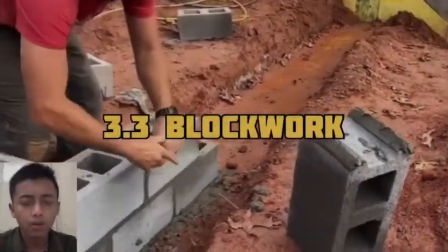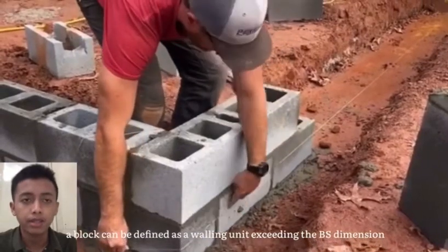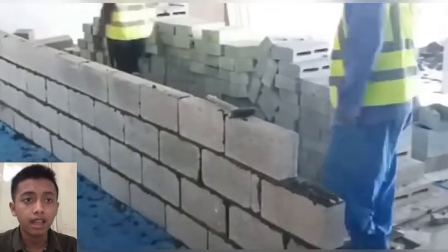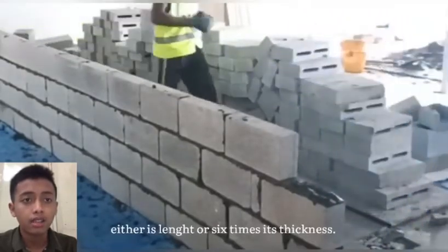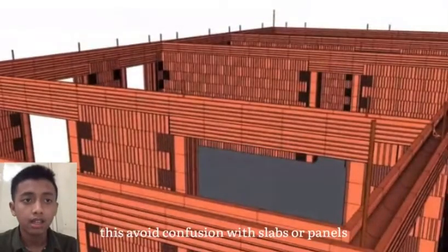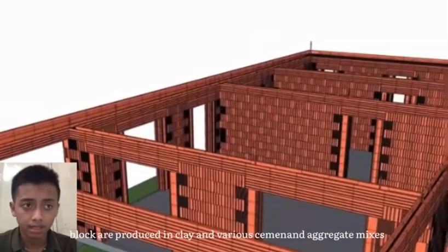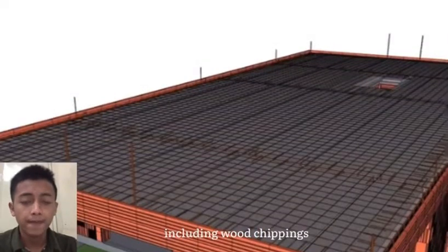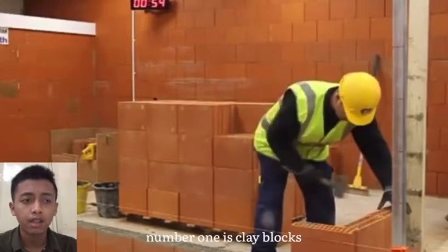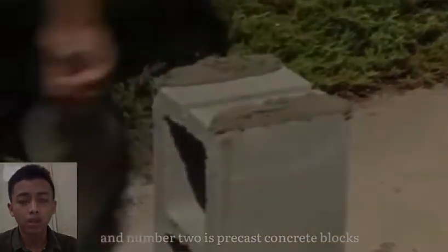3.2 Blockwork. A block can be defined as a walling unit exceeding the BS dimensions specified for bricks, and its height should not exceed either its length or 6 times its thickness. This avoids confusion with slabs or panels. Blocks are produced in clay and from cement and aggregate mix, including wood shavings. And the blockwork has two types. Number 1 is clay blocks and number 2 is precast concrete blocks.